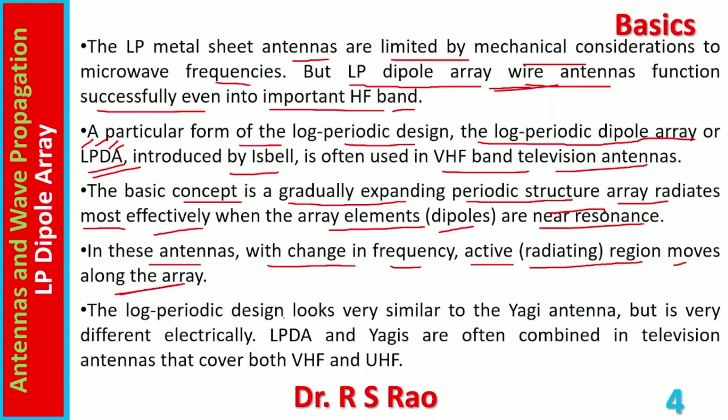The log periodic design looks very similar to a Yagi antenna, but is very different electrically. LPDA and Yagis are often combined in television antennas that cover both VHF and UHF. From a distance, it is very difficult to differentiate an LPDA from a Yagi.